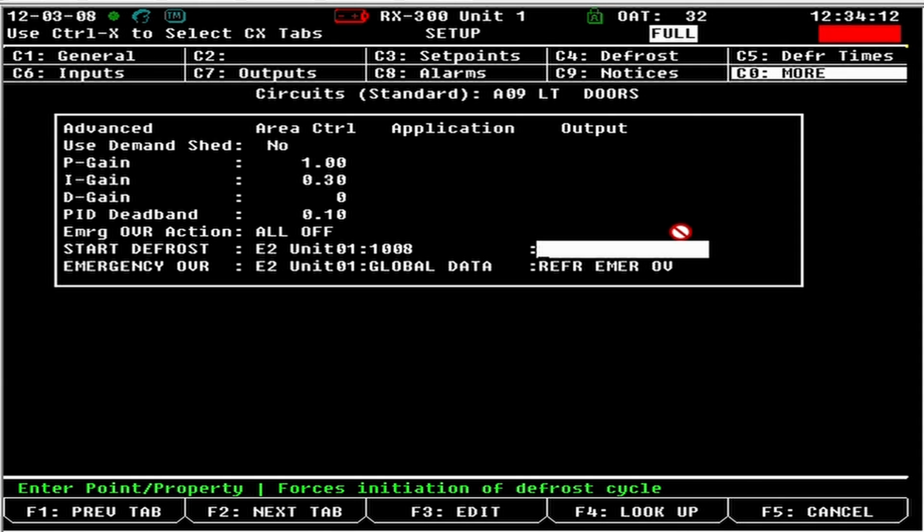So if it's A01A, A01B, A01C, A01D, and they're all their own zones, you would let them go to defrost all at the same time. So from A01 main, the defrost output would close, and then all these would go into defrost, and they would time out. It's a lot easier to do the alarms and everything else this way, because then everything starts defrost at the same time.